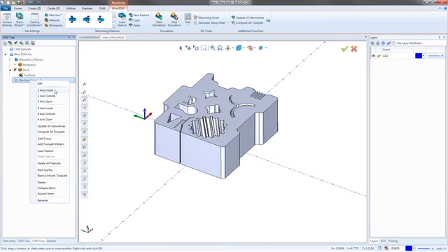And now you have a choice of a 2-axis inside, outside, or open. The difference between them is the settings that you get. You could pretty much do every part you want with a 2-axis open because it gives you both the punch and the die settings. So you get to choose whether it's a punch or a die. When you're doing a 2-axis inside, you're setting up the die. When you're doing a 2-axis outside, you're setting up the punch. I think I have that right, or you might need to reverse it, but I'm pretty sure.